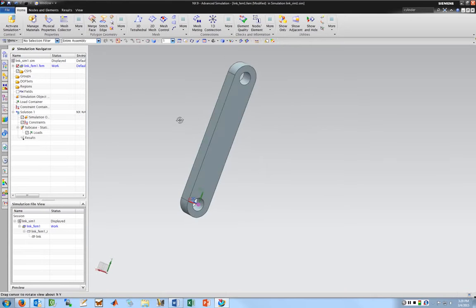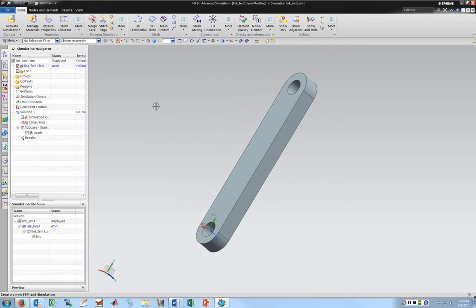First step, I've got my geometry that I've solid modeled. I need to make a finite element model. For a 3D part with this kind of configuration, I probably want to do a 3D tetrahedral mesh. For parts that are basically planes, a 2D mesh might work, or a series of planes or surfaces patched together. That might work. A 3D tet mesh is fine for this.